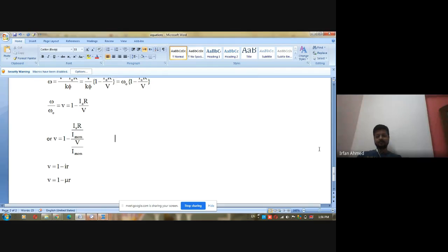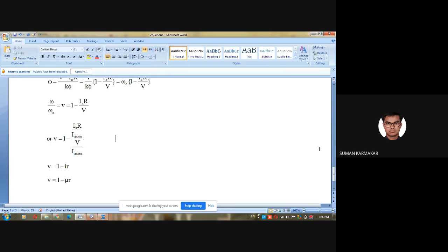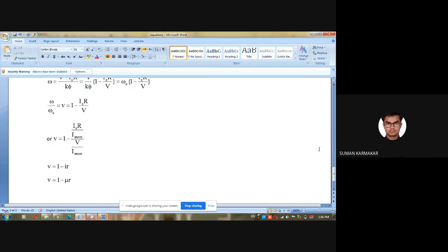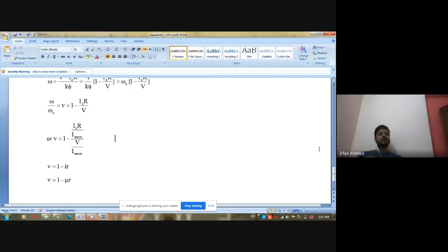Yes, anyone? Sir, it is a ratio of rated voltage with rated current. So it is only the armature resistance, not considering the external resistance. The resistance for which the current will be rated current when we apply the rated voltage.